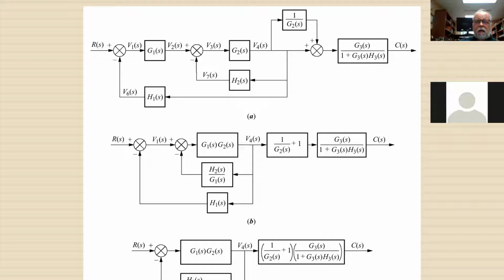So, when you combine, are you talking about parallel or series, or it doesn't matter? Right. So when things are in series like this, we multiply. When things are in parallel like this, we add. And then there's one other kind of thing that we call a feedback path. I'm going to be explaining the feedback path as part of Mason's gain, so don't worry about that. So when 2 things are in series like this, we multiply the 2 things together.